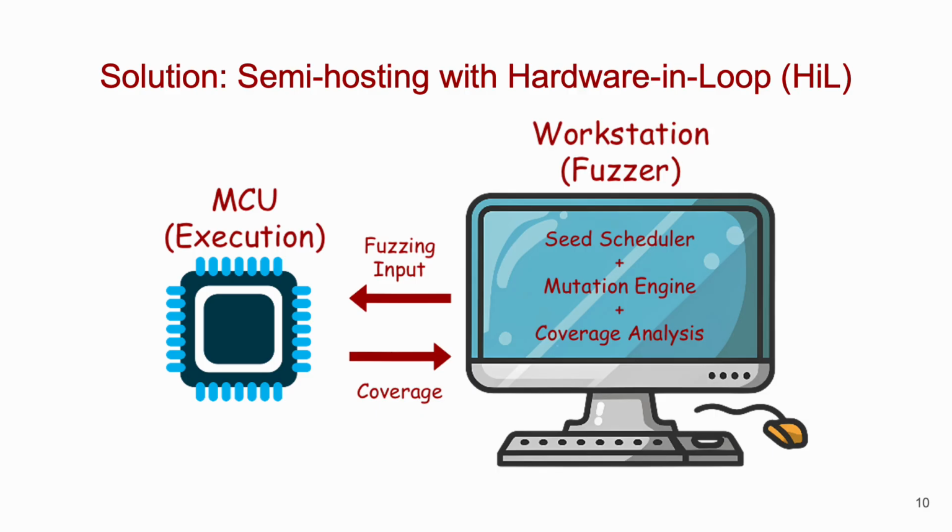To solve these challenges in rehosting frameworks, microAFL or mAFL proposes decoupling the execution engine from the fuzzer, which lets go of the emulator. In this framework, the execution of the target binary happens natively on the microcontroller, while the bulk of the fuzzing duties are done on the more powerful workstation using the popular AFL fuzzer. As such, the workstation now does not have to approximate the behavior of the hardware while observing real-time effects of complex interactions with the microcontroller peripherals.